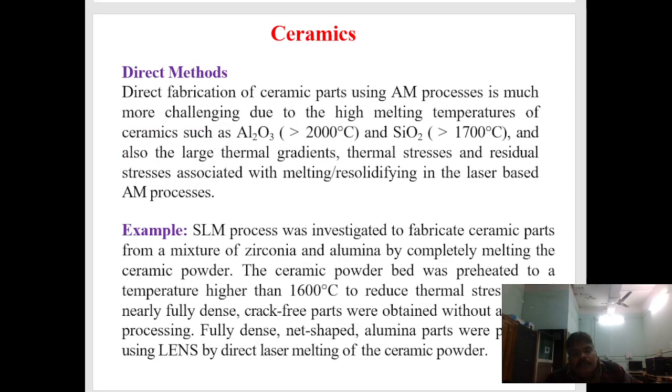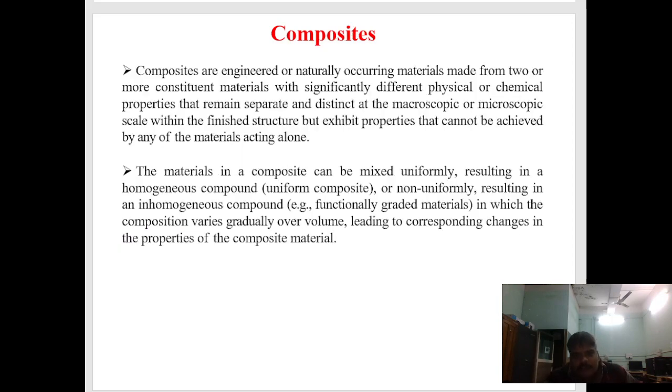Direct method: direct fabrication of ceramic parts using additive manufacturing processes is much more challenging due to the high melting temperature of ceramics such as Al2O3 and silicon dioxide, and also the large thermal gradient, thermal stresses, and residual stresses associated with melting in the laser-based additive manufacturing process.